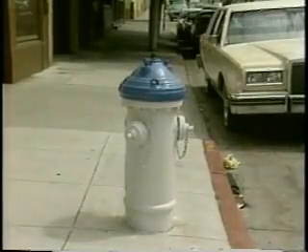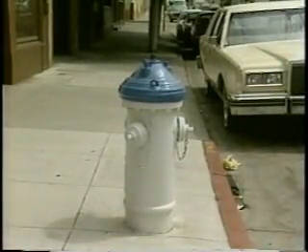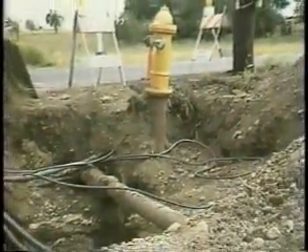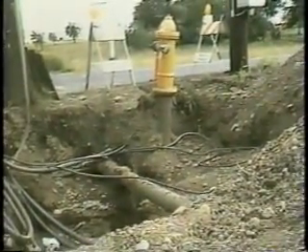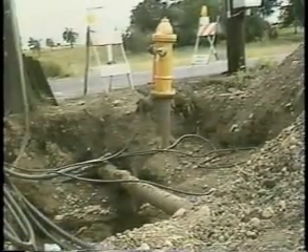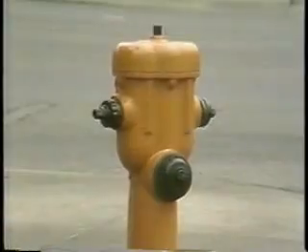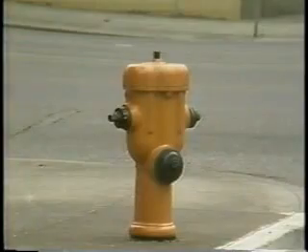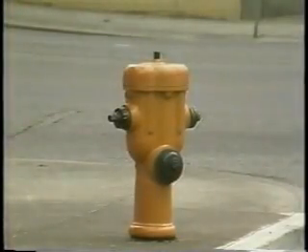Hydrants are found in a variety of sizes and shapes. Hydrants are nothing more than taps into an underground water distribution system. A valve enables you to open the tap, feeding water to the outlet ports. There are two basic types of hydrants, dry and wet. Dry hydrants have their valves located below the frost line. The barrel of the hydrant is dry to prevent damage through freezing.